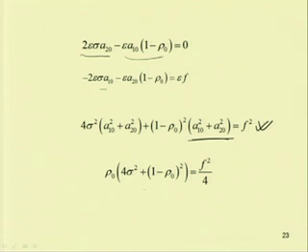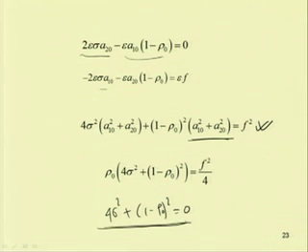This equation shows that if the external amplitude is equal to 0, this equation again reduces to 4 sigma square plus 1 minus rho 0 whole square equal to 0. So, this is the equation of a circle with center at 1, 0. For the case of external forcing equal to 0, one can find this frequency equation.